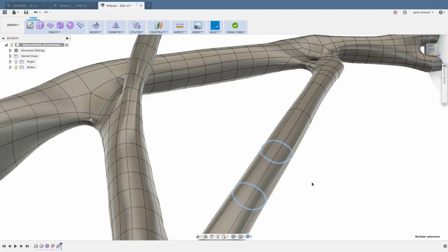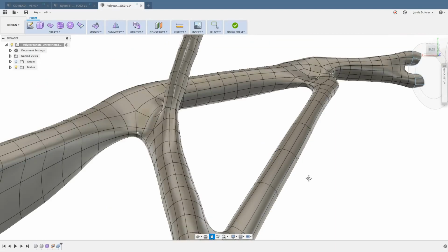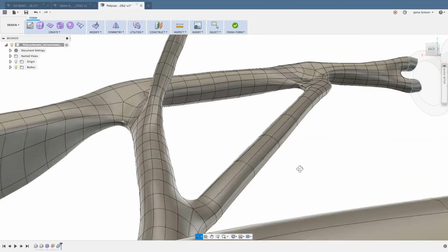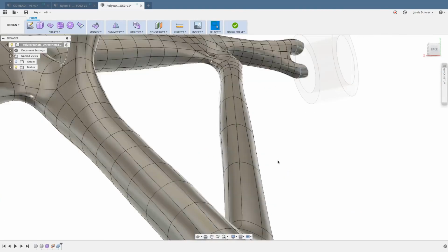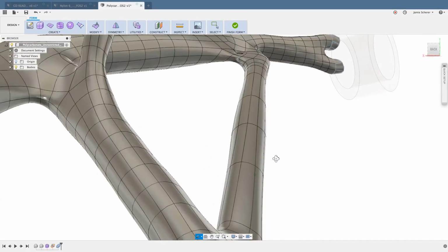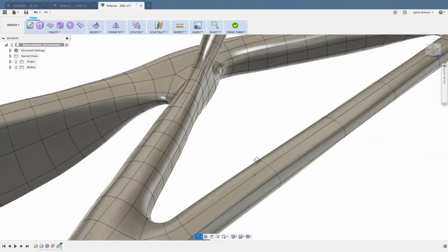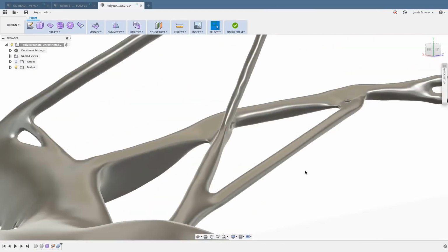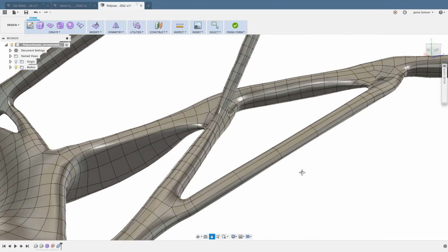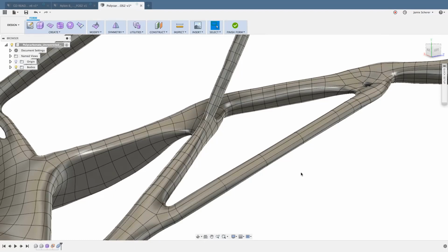The amount of spans or the edges between them is only one, where before we might have had 3 or 4, which was causing it to have lots of imperfections across that span. So just by deleting some edges, whoops, and we will try to get that so it's not in our way, you'll see this is already quite a bit smoother than it was before. But let's look at some other techniques, right? So deleting edges and having it automatically resolve for you is a great technique. But let's try something else.